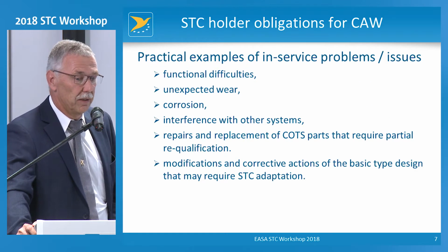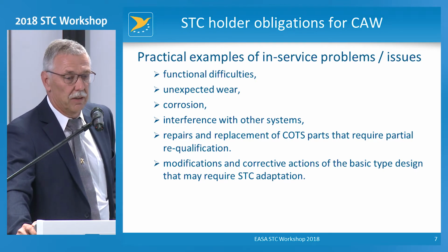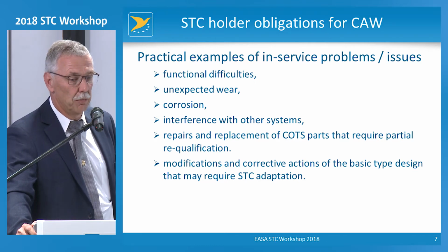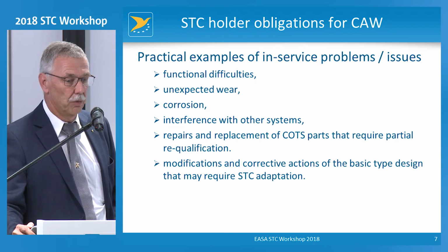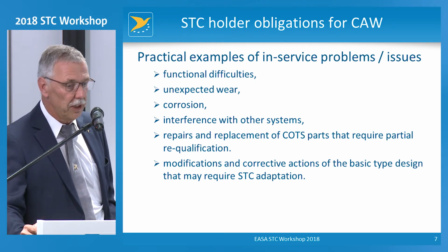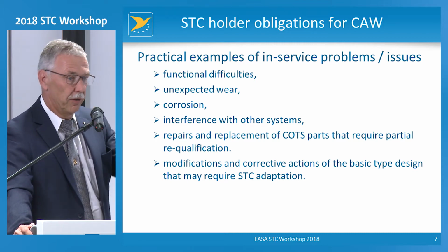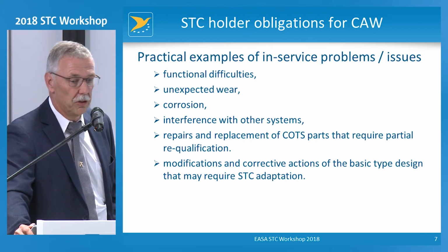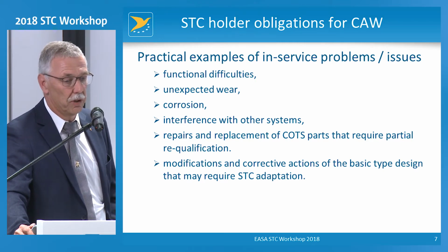So what is a list of potential problems that could happen in service? I listed just a few of them, and I will come later to the individual problems that I wanted to list. Functional difficulties, unexpected wear, corrosion, probably flying over water, over the sea with a mission airplane, interference with other systems. This could be electrical or probably even mechanical interference of the new parts installed.